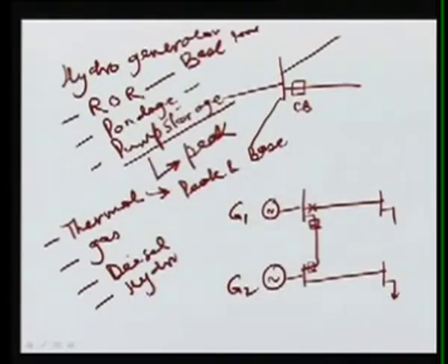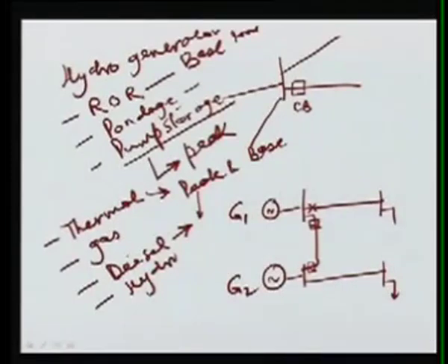plant. However, the diesel, as you know, the diesel cost is more than coal, so it always runs as the peak load power plant. Your gas is also very quick in starting. Here in the thermal power station, it is not quick in starting. Normally a thermal power station, if it is in the hot roll state, means it is running state, can require even 4 to 5 hours.